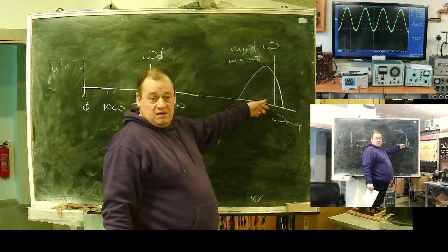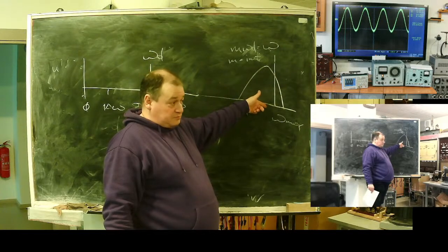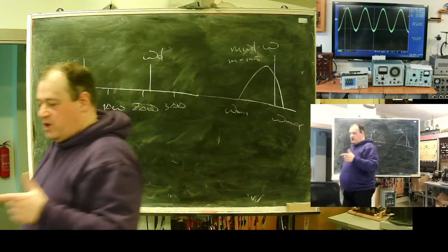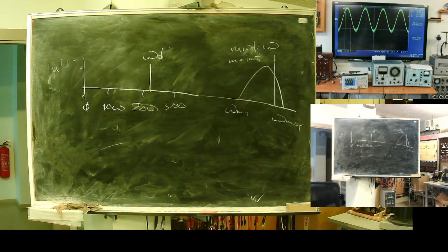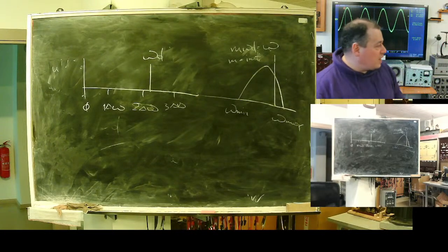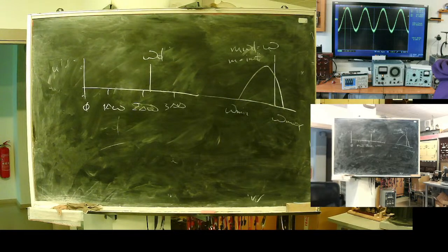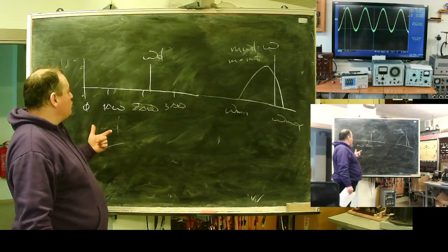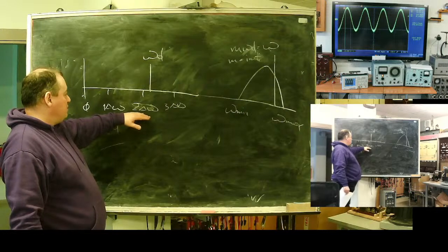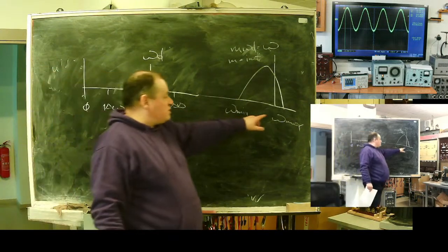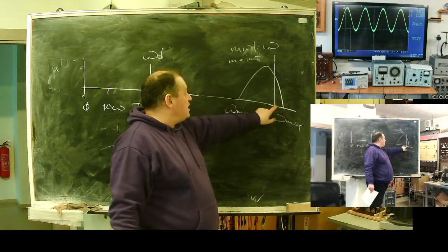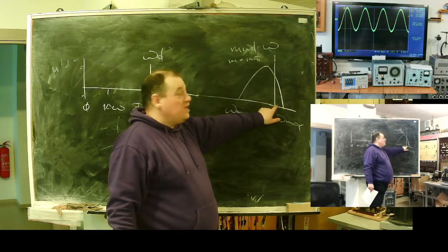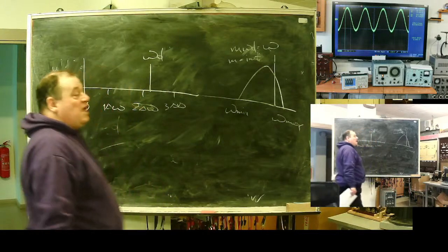Why are we talking about this? Let's say you have, for example, radio broadcasting. You have sound, then the sound is transferred to, I don't know, 100 megahertz and transmitted. You have a digital receiver. The digital receiver takes samples. If you do this basic approach and have a sampling rate above something like here, in your signal spectrum, we will have the spectral line being integer multiplied by the discretization frequency, and it will be distorted.